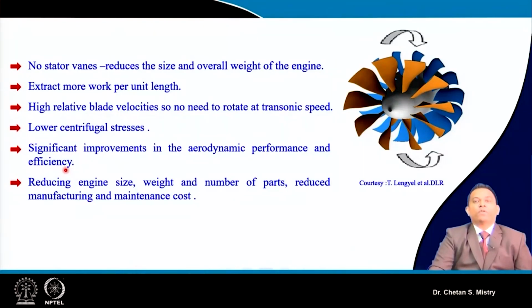So overall, by adopting this contra rotating concept, we are able to reduce the size, weight, number of components, and we are able to reduce the manufacturing and maintenance cost. And that's what is attracting the use of this contra rotating concept for engines. A whole lot of research and development activity is going on for application of this contra rotating fan for, say, aero engines.